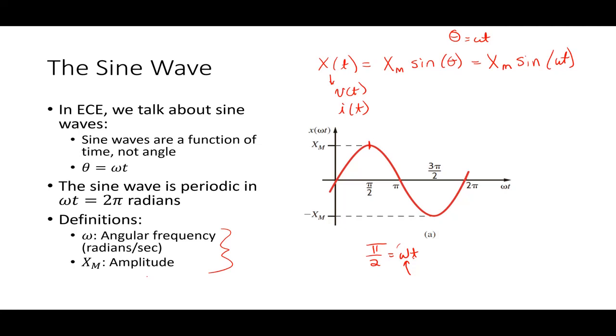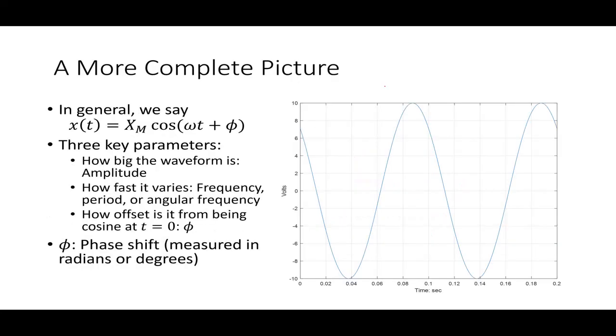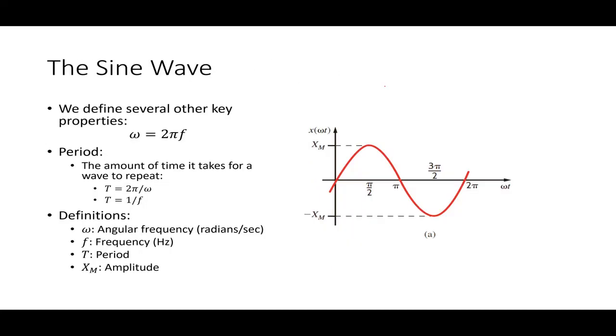So you see that there's two key parameters here. All right, so there's ultimately 3 parameters that we'll think about, but essentially what I call the angular frequency tells us how fast this guy repeats, and that guy has a unit of radians per second. How many radians is it changing per second? And then x sub m is the amplitude. Okay, so it's critical to remember that we're talking about voltages and currents, and those voltages and currents are changing as a function of time. All right. So a couple of things for us to remember here when we're talking about these things.